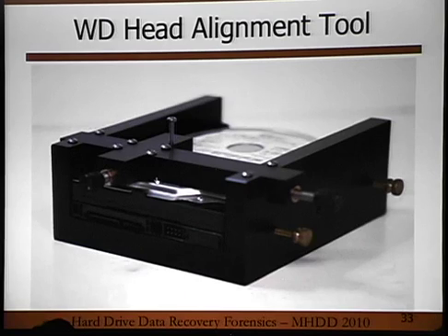Now, luckily for us, with the new Seagate hard drives and the Western Digital drives, most of the time it is almost always a firmware or a board problem. Anything made since maybe 2006, 2007, 500 gigs, terabytes up, any of those are almost always a board problem of some kind. Not that there are no head problems, but they are rarer than you would think.